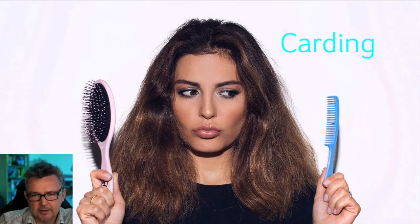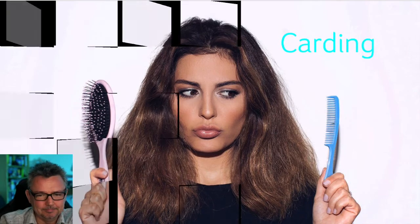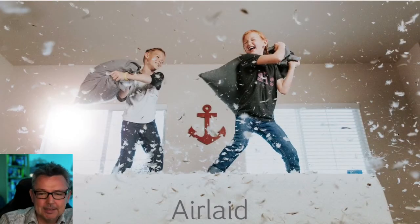So, very briefly, carding. Carding is a technique where you effectively comb your fibres, separate them out to form a web. It works in the same way as brushing your hair or combing your hair does, but it's using big rollers with pins on them. It orientates the fibres in one direction predominantly, just like brushing your hair does. Airlaid, you blow your fibres into air and let them settle down because they land relatively randomly. They're not oriented in a certain direction like carded fibres are, and therefore the resulting fabrics have very different properties.